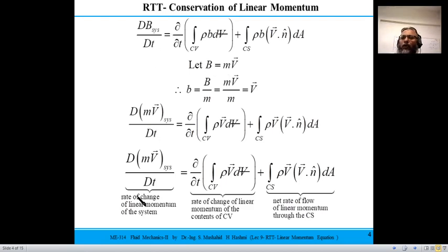an expression. So that would result in a momentum equation, and because the left hand side is a vector, it is actually a vector equation. This is the rate of change of the linear momentum that is taking place within this control volume. So this thing is mass per unit volume. Volume and volume cancel out, so mass multiplied by velocity would be momentum. So this is the momentum of a differential volume. If you integrate it over the whole control volume, it is the momentum that has been accumulated within the control volume. And once you differentiate with respect to time, you are interested in the rate at which the linear momentum has been changing within this control volume.